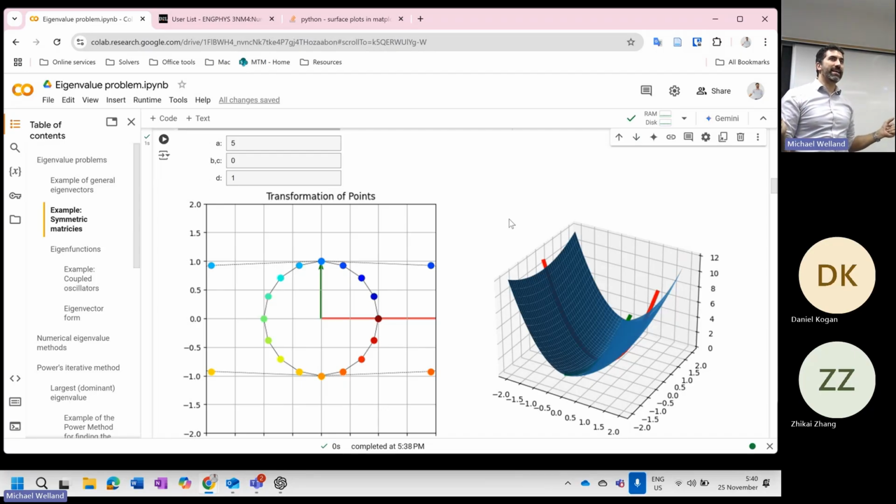A good example for that is elasticity. Incompressible elasticity has a problem: normally if you displace a piece of material a little bit, you get this restorative force, right? But if you try and displace everything around a circle together, then you get this huge restorative force because you're incompressible, effectively infinite. You get an infinite Hooke's constant, right? That causes a lot of instability or stiffness in your problem.